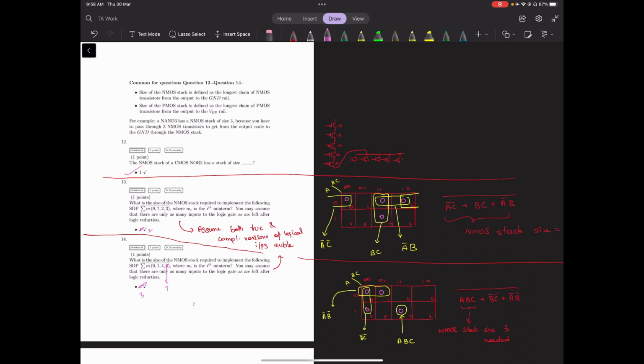In the next question we are given this sum of product expression, the expression of min terms. And since it's a complement expression, we can just implement it directly in CMOS. If you look at the K-map here, where I've put zeros because it's a complement expression, you will see finally that it reduces to the following sum terms 1, 2, and 3.